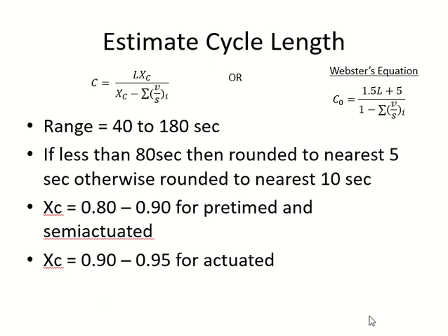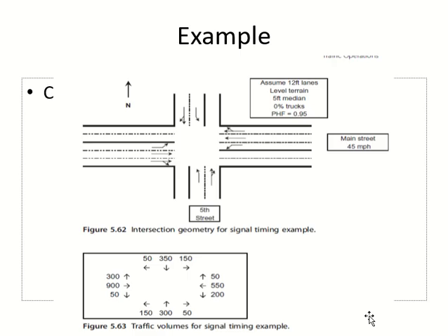The next thing is, we should identify the lane groups. Now look at this, they are similar, right? These two are similar. How many lane groups do I have here? 2, right? They cannot be in the same group because they have different movements. I have 2 lane groups here. What about this one? How many lane groups here? Again, they are similar, so whatever you say here would be applied here as well. 3, right? The 3 lanes and all of them have different movements.